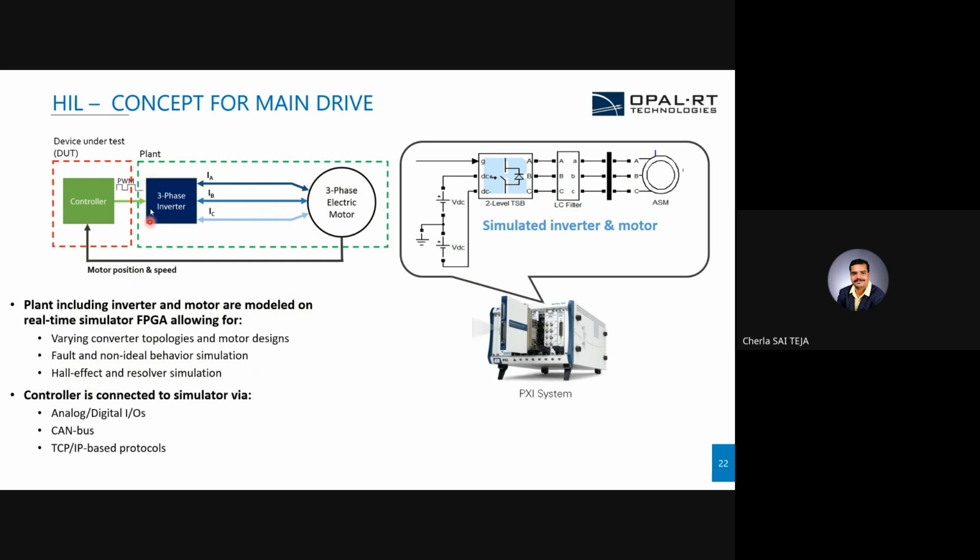So I can happily short one leg of the inverter by sending the same pulse to the top switch and the bottom switch. I can see under this fault study how the motor will work, or what happens to the motor. So all this non-ideal behavior we can happily simulate and study for various topologies.